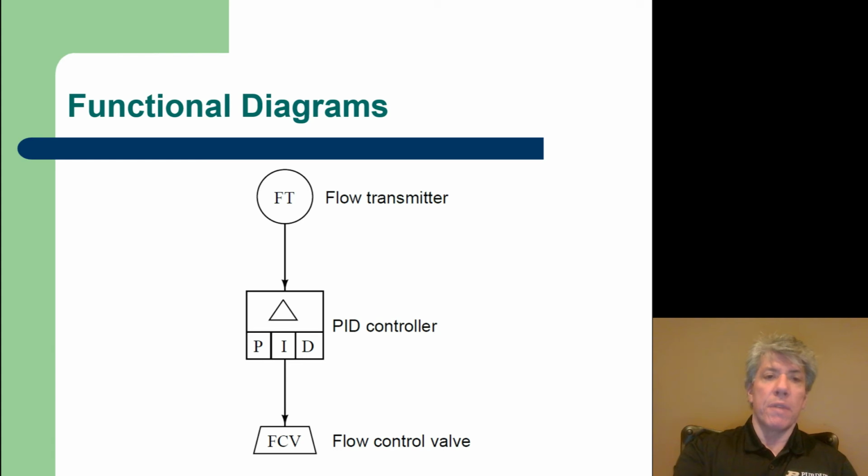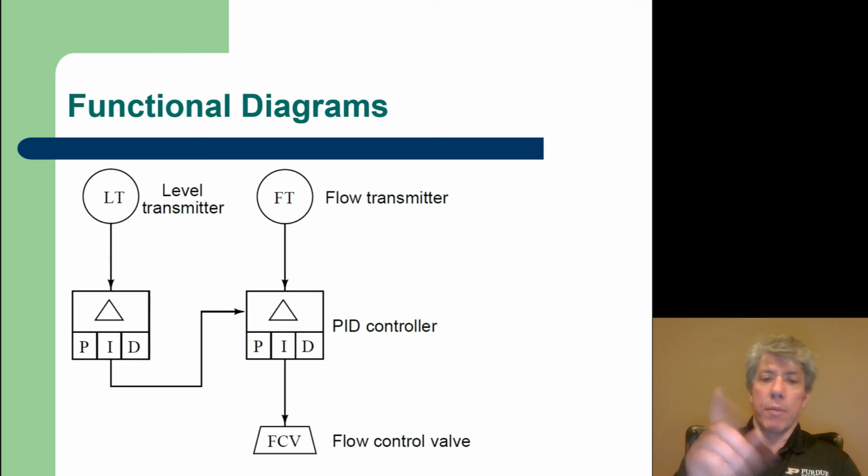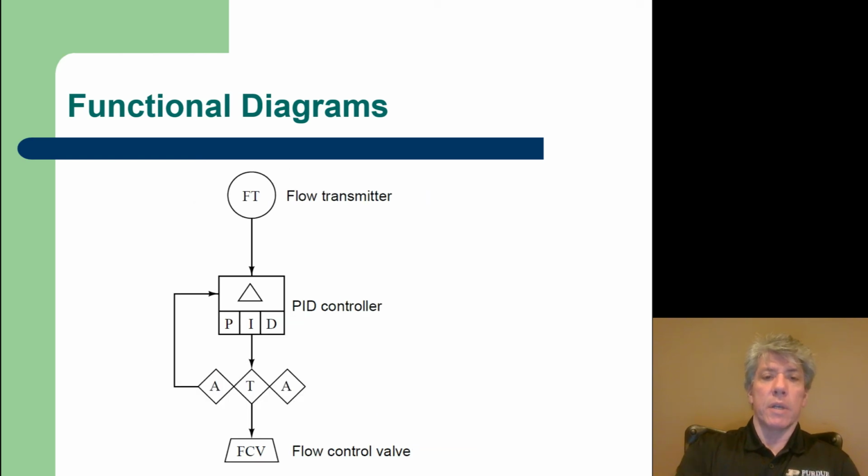It's a very simple feedback control system, and you can see what this does. It's labeled as a PID controller. The symbol makes that obvious. We can even indicate a cascade control, as you see here, where the level, say, in a tank is measured, and there's a primary controller on the left that is doing PID control and provides the set point for the flow PID controller on the right. And so this is a classic cascade setup, and it's easy to see that that's what it is.